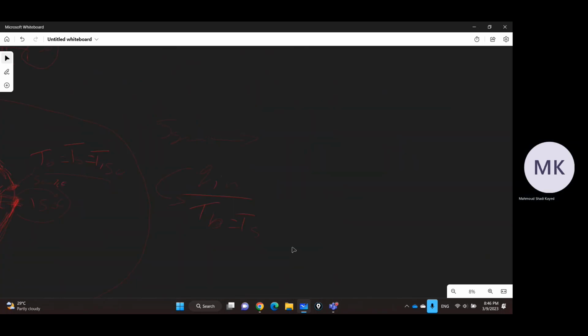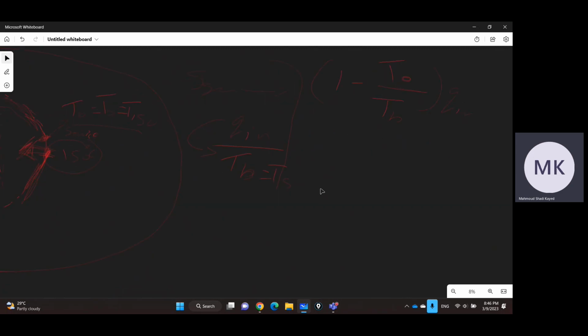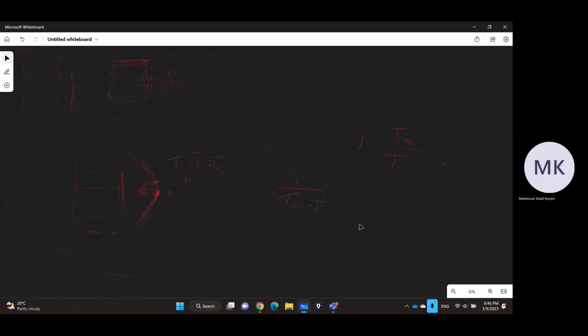Now, this we don't have any problem with, but for the Exergy, it will be Q times one minus T naught over the boundary temperature. Here, the boundary temperature, unlike the previous question, is not the same as T naught, so you cannot say T naught over T boundary equals 1, and 1 minus 1 is 0.